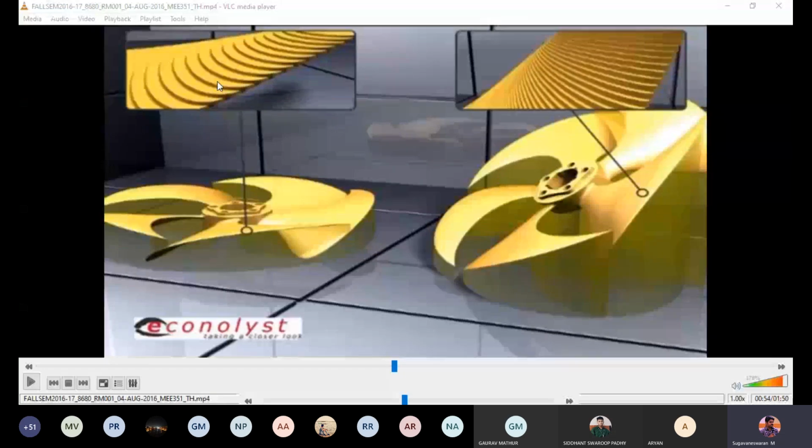Though it looks like a 3D model, when you stack multiple layers, layer by layer, the surface will not follow a slope angle of less than 20 degrees or greater than 80 degrees, because in both extremes you have an advantage. If the slope angle is less than 20, then you will have an advantage in the x-axis. If the slope angle is more than 80, you will have an advantage in the y-axis.